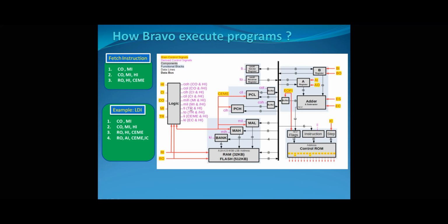Now, another interesting case here is in regard to our RX and TX module in our UART module. If you look at the control logic here, and I'm sorry, it's a little bit small, we're going to have a look in detail at all of those signals later. But for now, we have only one output from our control logic for the send and receive, and that's called the TR signal.